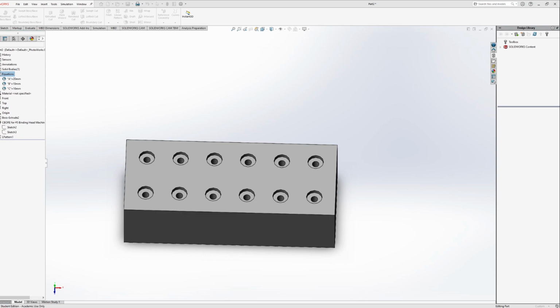I believe I go through it a little bit in the PowerPoint, but the main thing here is that we actually are able to just select a specific sketch and then select the dimension or a respective dimension on that sketch, and then assign appropriate equations to that. So if we notice that maybe a specific equation or a specific measurement should be 5a, well, we can actually assign it from this window. We don't necessarily have to assign it from the Smart Dimensioning window itself when we're actually dimensioning a sketch itself.